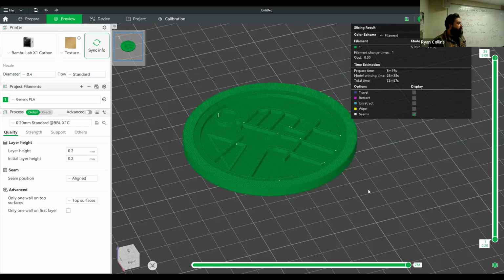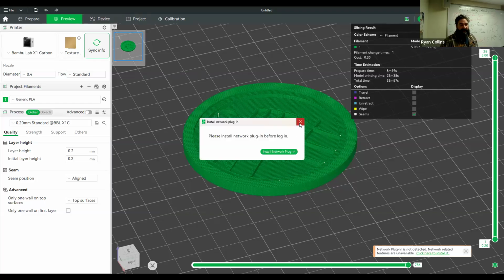Yes. With the makerspace, do you have to babysit it as it goes? No. The question is, do you have to babysit these? The standard is usually, once you get these started, you want to hang around for the first layer to make sure it sticks properly, because sometimes little things happen. The first layer is the most important layer, because if it craps up then, obviously that can screw the whole print up.